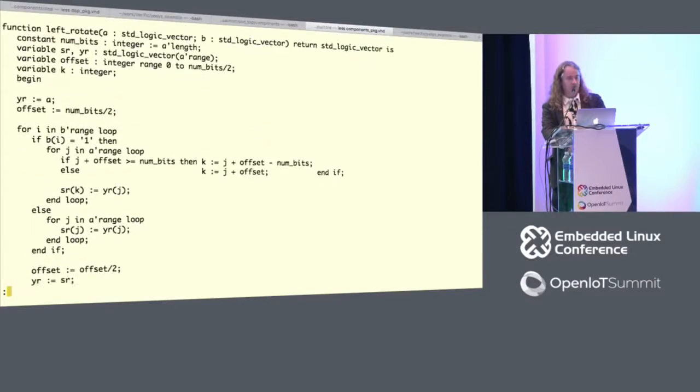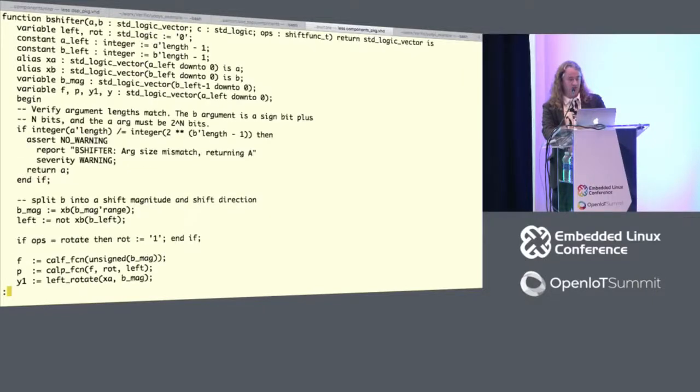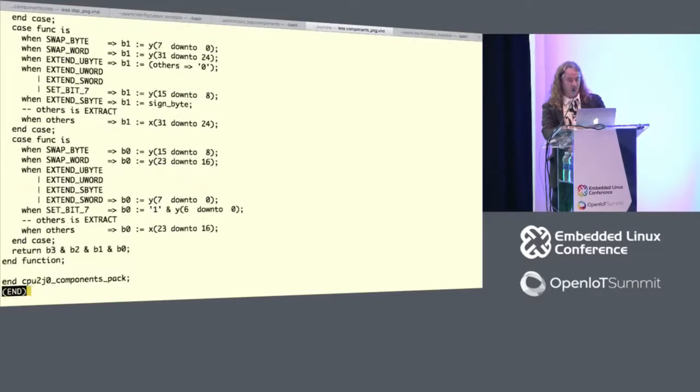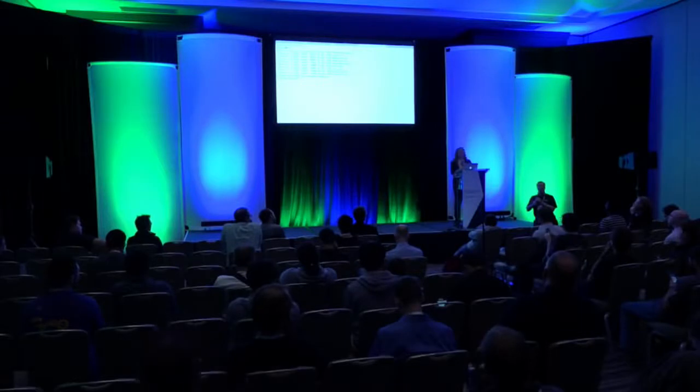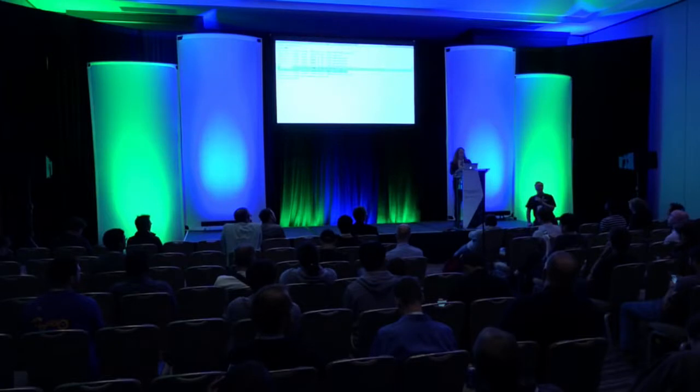The barrel shifter needed to be very compact, and so the implementation is a little bit difficult to understand. That was a feature we backported from SH3 to SH2? The barrel shifter, there was a bunch of research papers that we looked at, and sort of a combination of a few of them. It's a left shifter, but anyway, it does a lot of really interesting things. As patents expire, we do add more features. It's just SH2 shipped an awful lot of units. SH4 shipped an awful lot of units. SH3 was overshadowed by SH4 after about a year. It didn't have a long life.